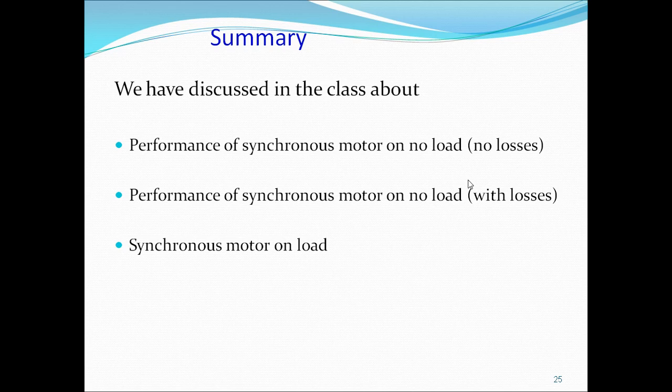But there is a limitation for this load angle. If the load angle increases beyond 90 degrees, then what happens? The motor comes out of synchronism and the motor stops. The torque at this moment, where the motor comes out of synchronism, is called the pull out torque.